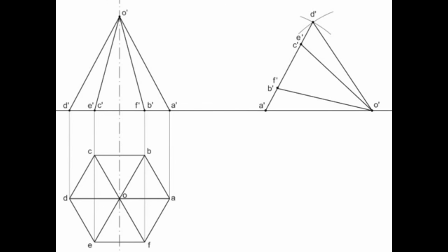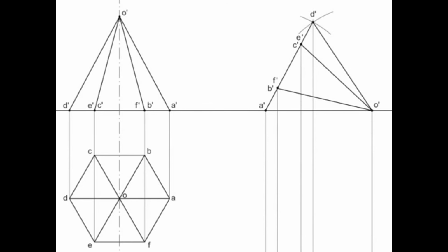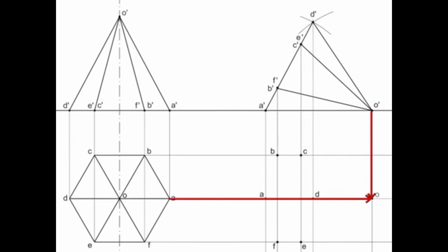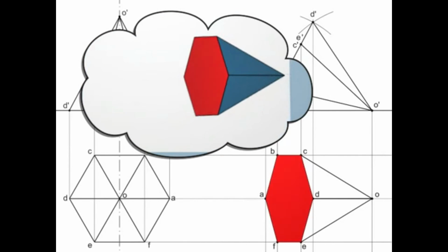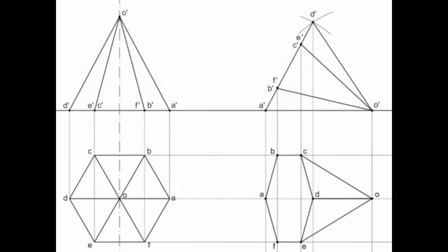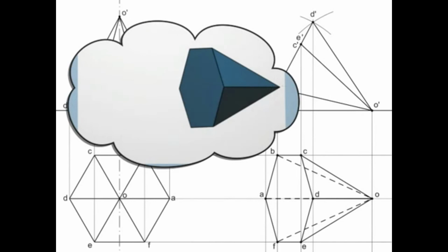So let's generate its projection. Draw the projectors in the downward direction. Also, take the projections from the previous plan. Locate and connect the intersecting points as A, B, C, D, E and F. See, the base is visible from the top. We will be getting the hexagonal base. Lines crossing the base, AO, BO and FO, will be dotted as they are hidden.